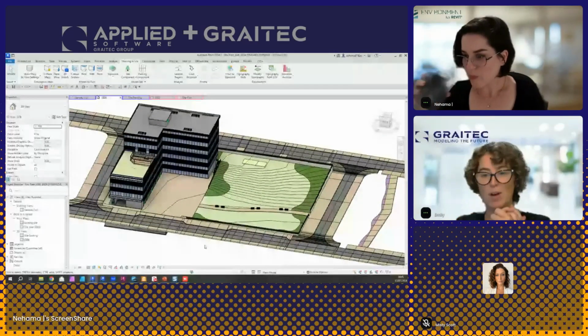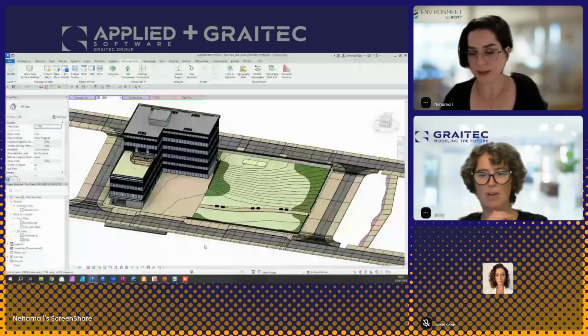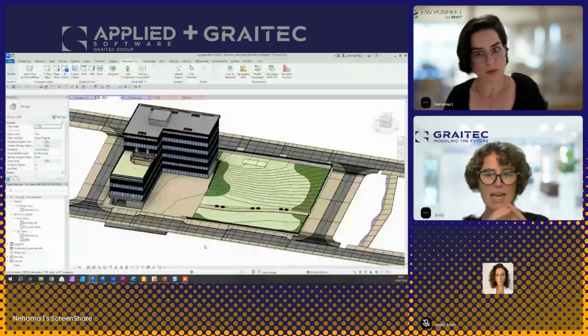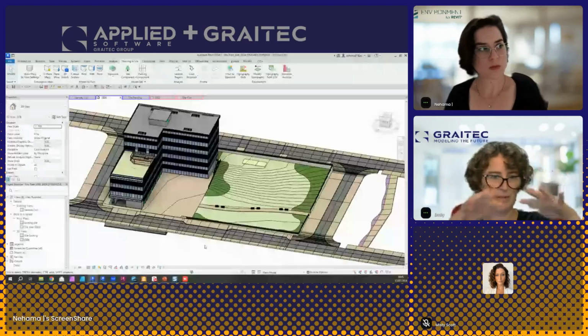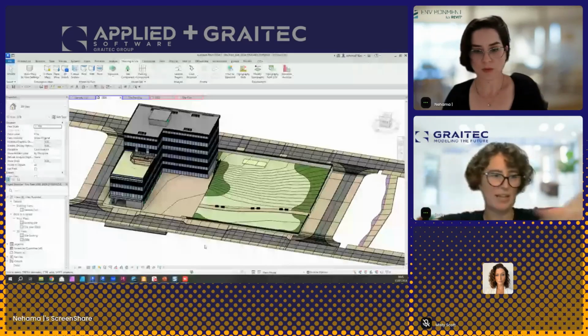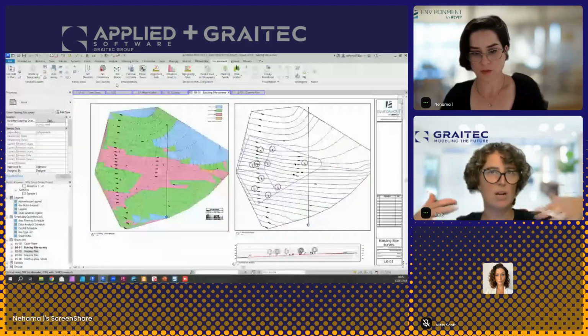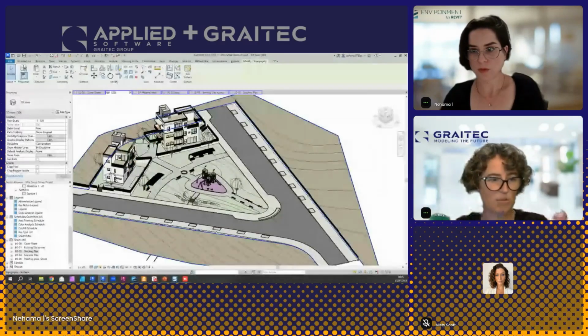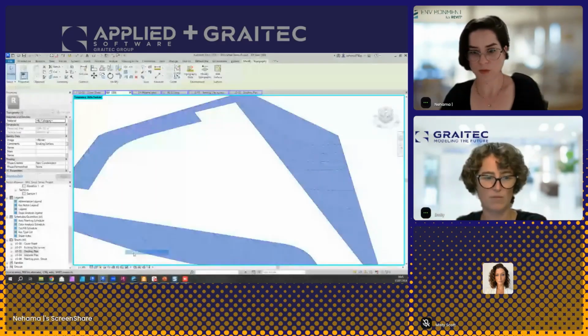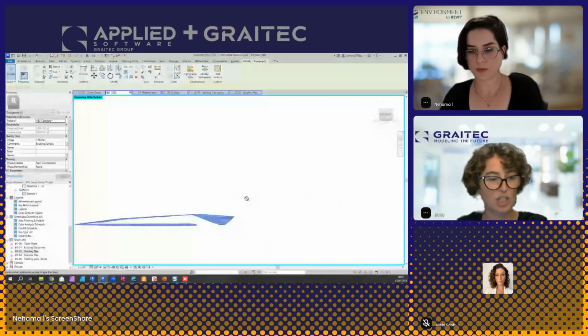So, all right. Now, there's a number of people that have asked about topo surface versus topo solid. So I'll just cover that one briefly. Topo surfaces are like tinfoil. That's it. You have a surface, but you have no depth to it. You can't control the layers. You have no visuals when you cut a section through it.